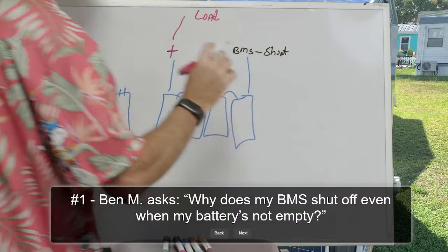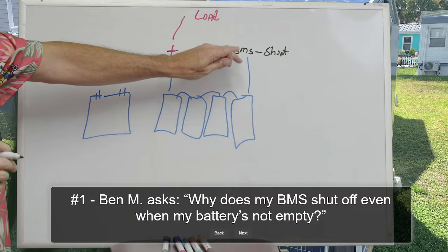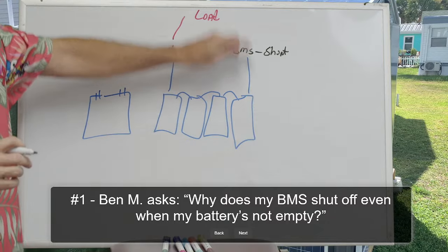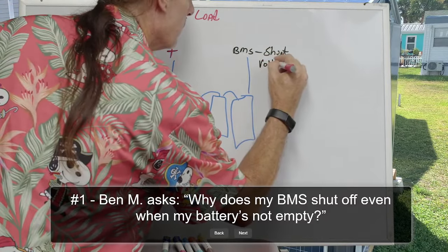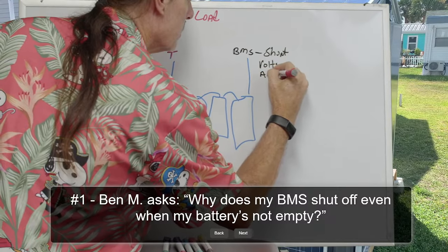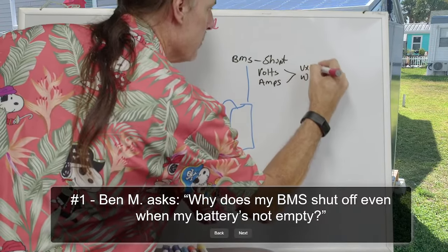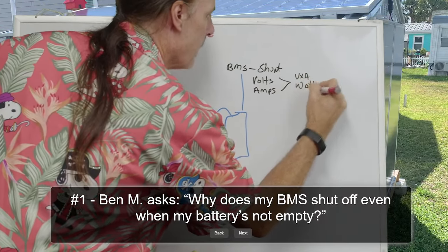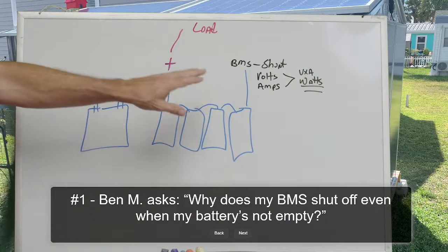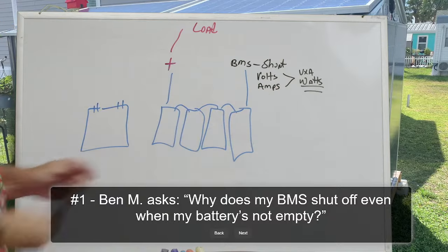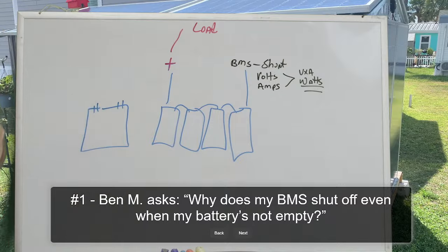Now, this shunt is not any different than your typical shunt. It is basically measuring the power in both volts and amps, or volts times amps equaling your watts. It is this measurement, just like it is for a Victron shunt, that allows you to determine what your state of charge is. Now, keep in mind, this is a net addition.